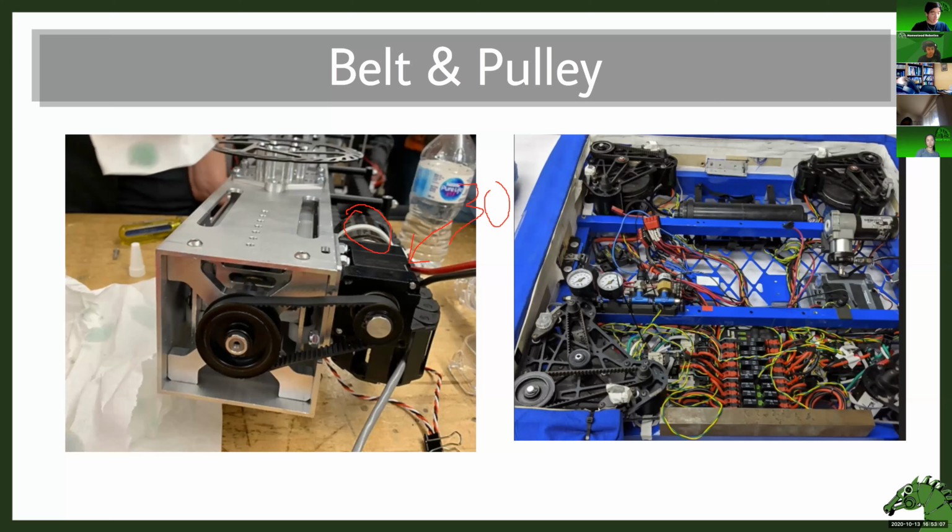So the key thing here is they could attach this motor straight on here, but that packaging is not very good. The pivot looks like it's up here. You don't want too much swinging around the back, and it's not very safe for the motor to get hit off the back. It's a really easy solution where they just bolt the motor to the side of the arm and use a belt. By using that belt, they can use a small pulley here and a slightly larger pulley here, and actually get reduction.